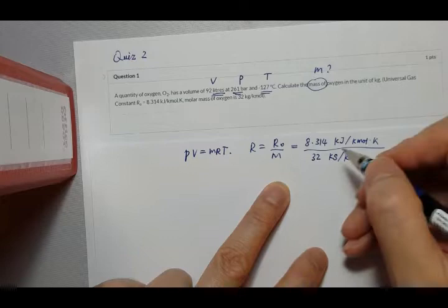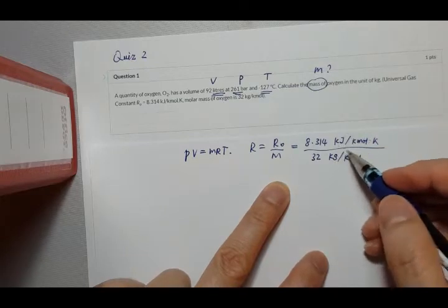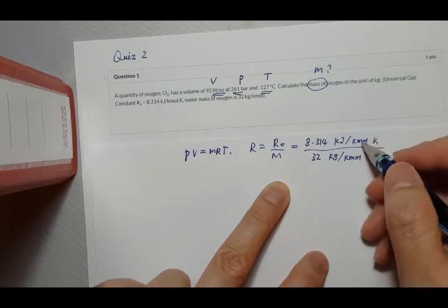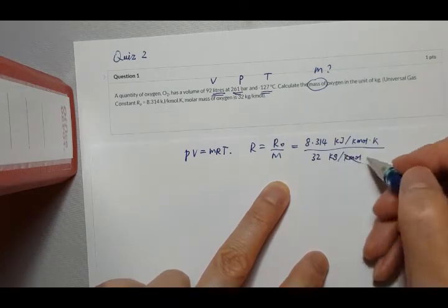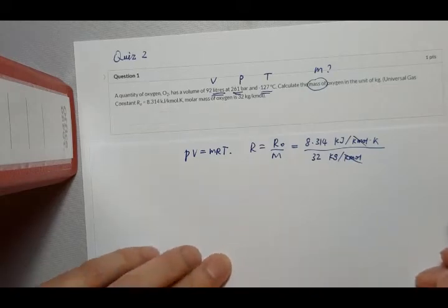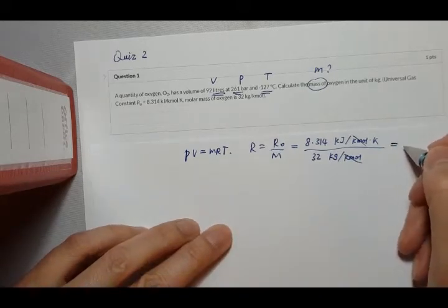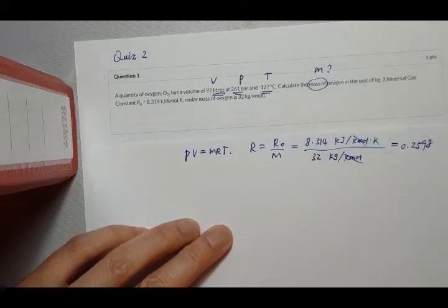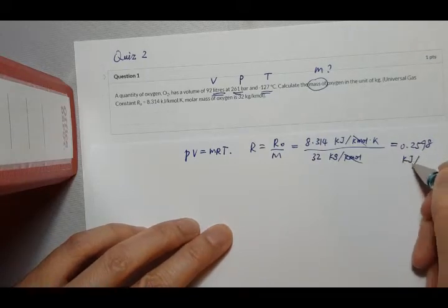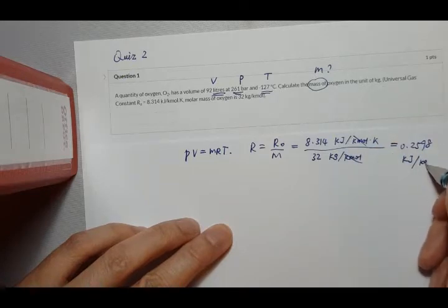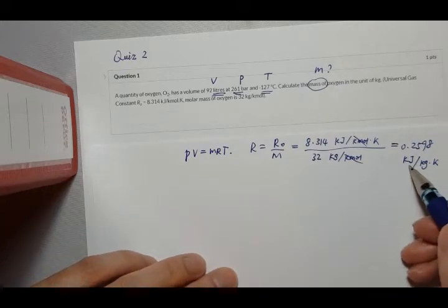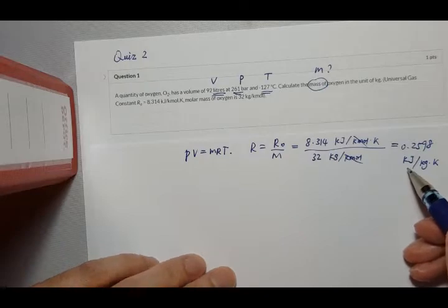If we put the units behind all the values, you can double check the final unit. We have kilomole here, and these two will cancel. So the final answer will be that with the unit. Be careful about the unit, it is kilojoule per kilogram K. You need to pay special attention here because this is a kilojoule. Bear in mind, kilojoule is not an SI-based unit.